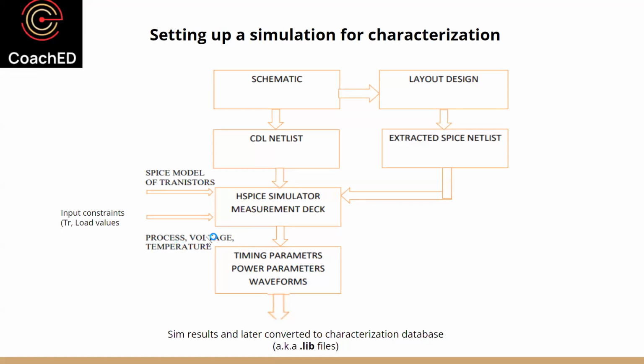Voltage is very clear because, as we saw earlier, the delay and currents depend on voltage. So you need to set what voltage, whether it's 1 volt, 1.5 volts, 2 volts, 0.6 volts, or whatever. Your choice, that comes from here. That's your specification. Temperature, again, could be 100 C, 50 C, 0 C, depending on what your customer requires, or where you want to test the circuit.